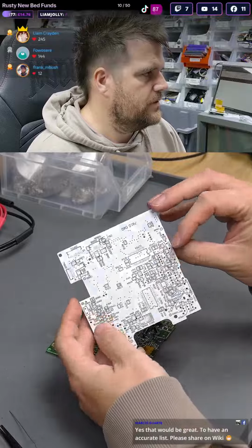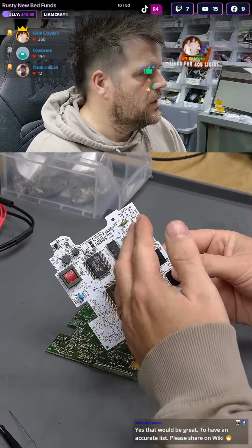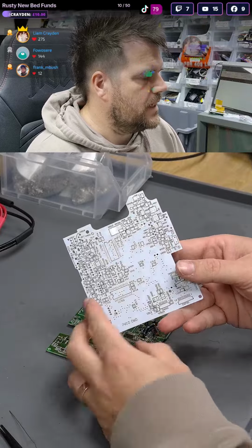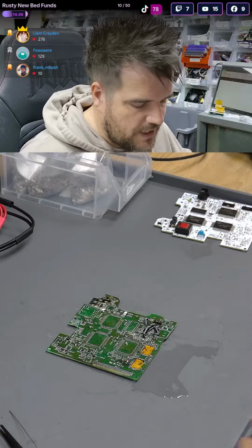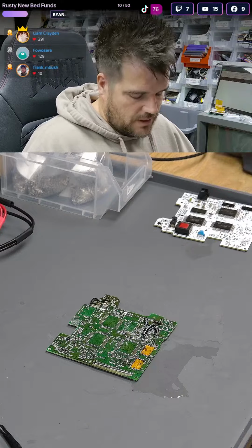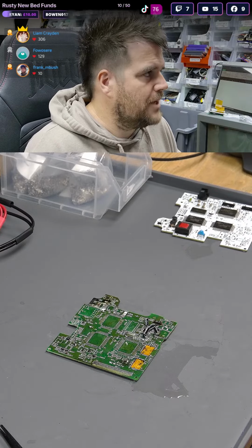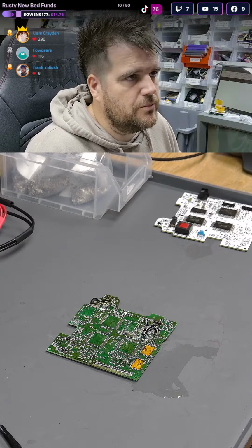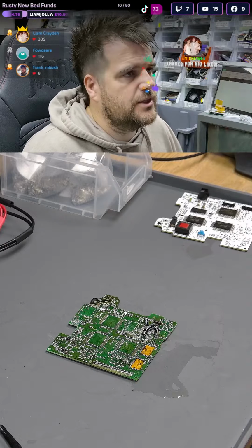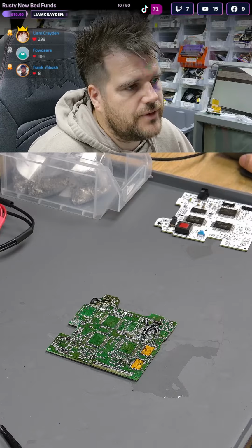We're transferring very slowly every component all the way over onto the board, working our way down this front side and then tackling this disastrous back side after. But we're testing every single component as we go, to measure the values and figure out what they are, so that we can have the factory assemble the boards for me in future, and I don't have to swap all the resistors and caps over every single time. I can get most of it pre-assembled at factory.